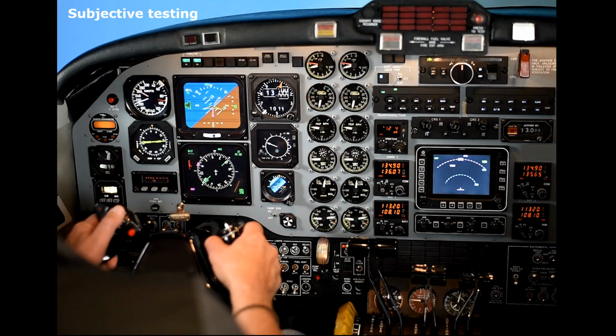Subjective testing is performed by a pilot with the appropriate license to fly the simulated aircraft. The pilot should also be knowledgeable about the FSTD technical requirements to understand what is expected from the device in question. In short, subjective testing involves flying the training device and using all your senses to evaluate if the device feels appropriate and supports positive training.